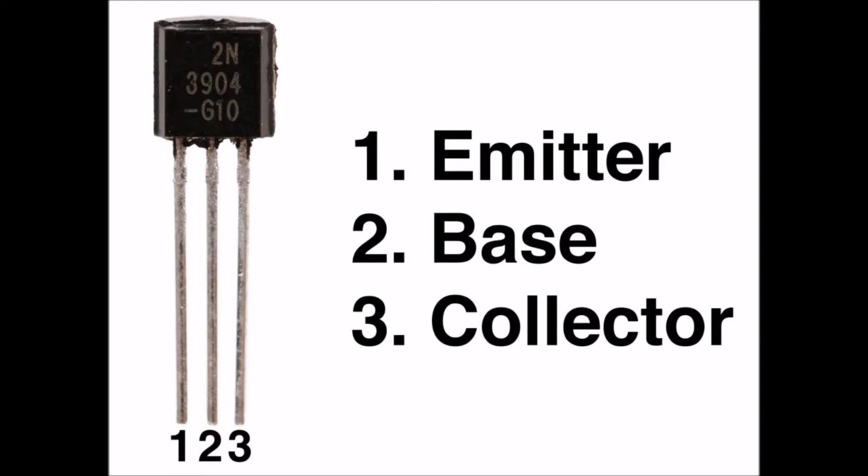Despite the reverse bias of the BC junction, a significant emitter-collector current, called collector current and denoted IC, flows through the transistor once the EB junction conducts. In a real transistor circuit, such as the one shown in figure 22.3b, the meter reading will jump when we apply DC base bias to reach and then exceed the forward breakover voltage of the EB junction. If we continue to increase the forward bias at the EB junction, even a small rise in EB, attended by a rise in the base current, will cause a large increase in the collector current, IC.